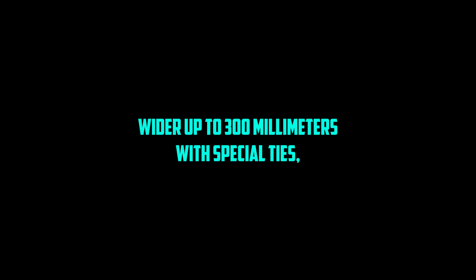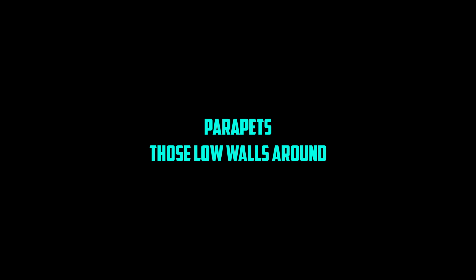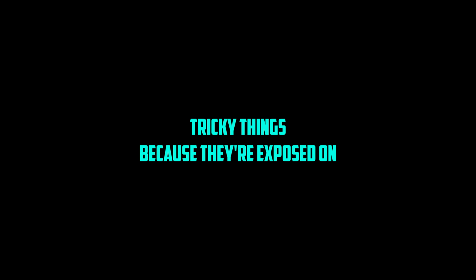Very much so. Typically a 50-75 millimeter gap, sometimes wider, up to 300 millimeters with special ties, usually sealed top and bottom, not ventilated. Stainless steel or non-ferrous wall ties are preferred now over older galvanized ones, less risk of corrosion. Parapets, those low walls around flat roofs or balconies. Tricky things because they're exposed on 3 sides, front, back, and top. Need really careful detailing to keep water out and ensure they last.